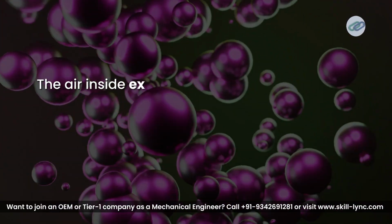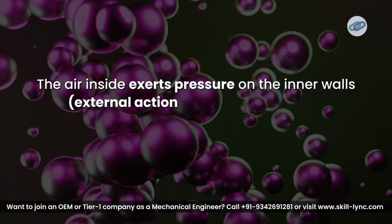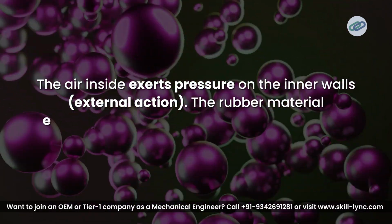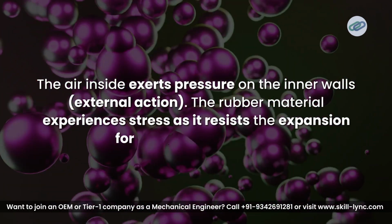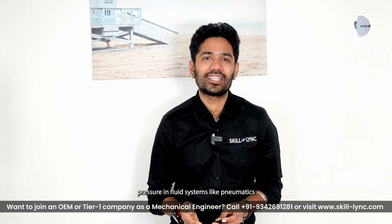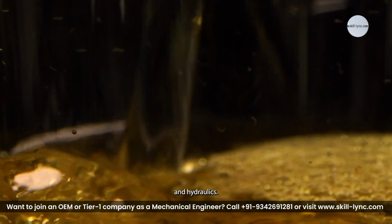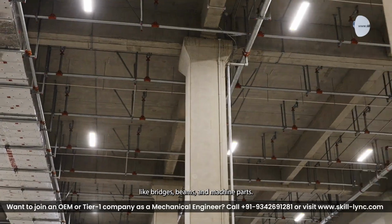Think of a car tire again. The air inside exerts pressure on the inner wall. This is an external action. The rubber material experiences the stress as it resists the expansion force, which is an internal reaction. This difference is why engineers consider pressure in fluid systems like pneumatics and hydraulics, while stress is analyzed in solid materials like bridges, beams, and machine parts.